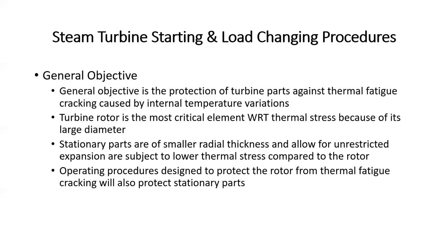As we heat up a rotor and cool down a rotor, it goes through these alternating stress cycles. If you start cold, go hot, and then cold again, on the outside surfaces, you go into compression, and then you go into tension, and you come back to the same position when everything cools back down to room temperature. On the bore location, down on the inside surfaces, you go from tension to compression.